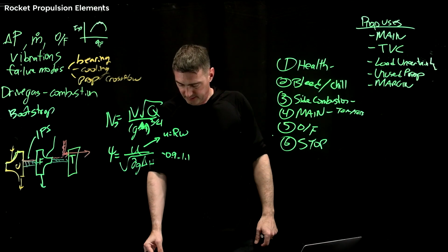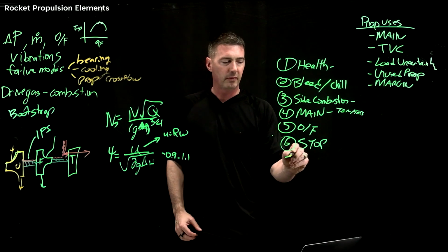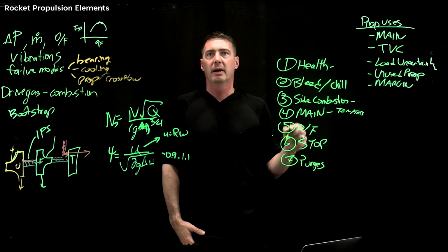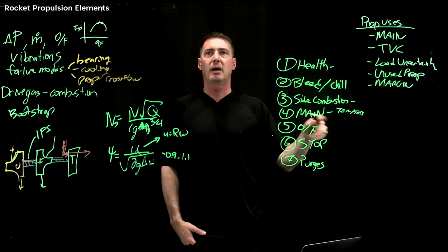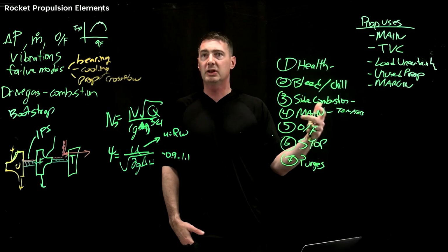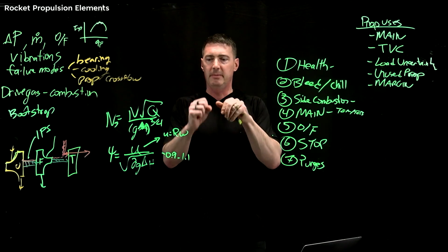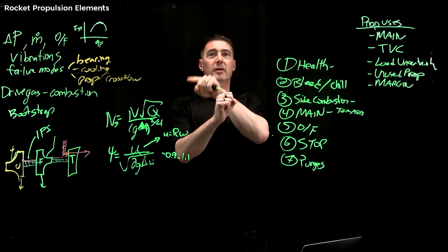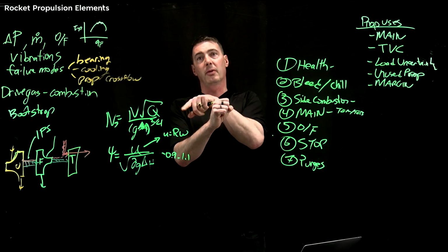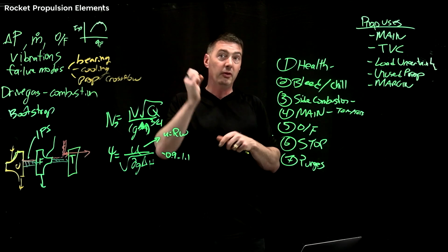Okay. And then all along the way are purges. And this can be to clean out lines, make sure there's nothing in there on a stopping process. Second stage engines usually have to relight. So again, back to orbit, you get to orbit, but your orbit's elliptical. And so you actually have to burn again 45 minutes later on the other side of the Earth to circularize it. So especially on an upper stage engine, you absolutely have to relight.